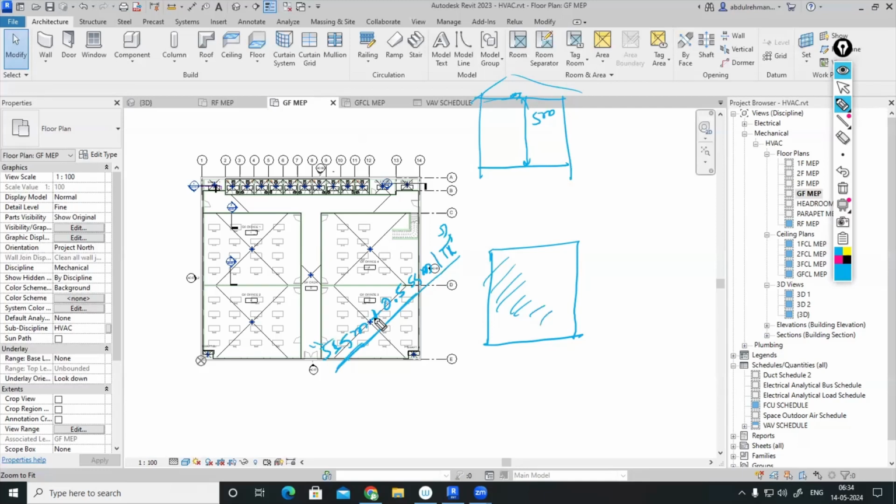For the chiller plant room, here I am planning to propose a water-cooled chiller only. Water-cooled chiller, we have discussed in the previous classes, right? We have a primary only system, variable primary system, primary secondary system, primary secondary tertiary systems. I'll be using a primary secondary system only. So primary pumps will come, secondary pumps will come. Then the cooling tower is a separate system for the water-cooled chiller. So how much space do we require? Roughly, if it is an Indian project or you are using a non-insulated wall, barely 140 square feet per ton of refrigeration you can consider as a thumb rule.